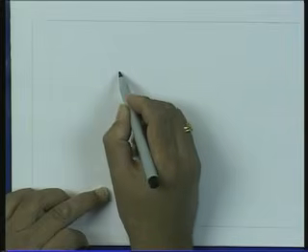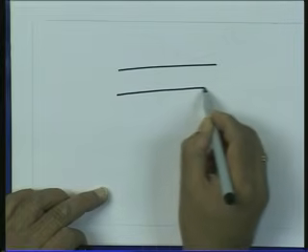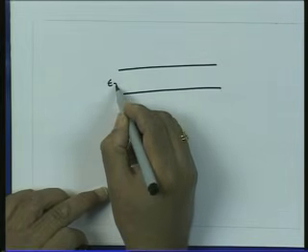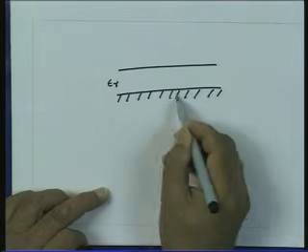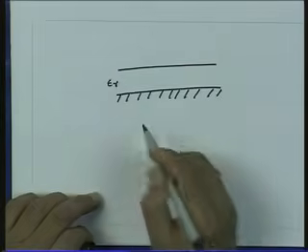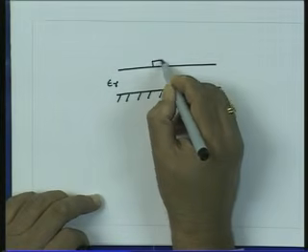The third structure which you see commonly in practice is what is called the microstrip line structure, and this structure normally is realized at microwave frequencies for making circuits. Also, whenever we have printed circuit board configurations, you have this kind of transmission line. So, this structure is a dielectric slab whose dielectric constant is epsilon r, which is plated with a conductor on one side, and there is a strip of metal on the other side.